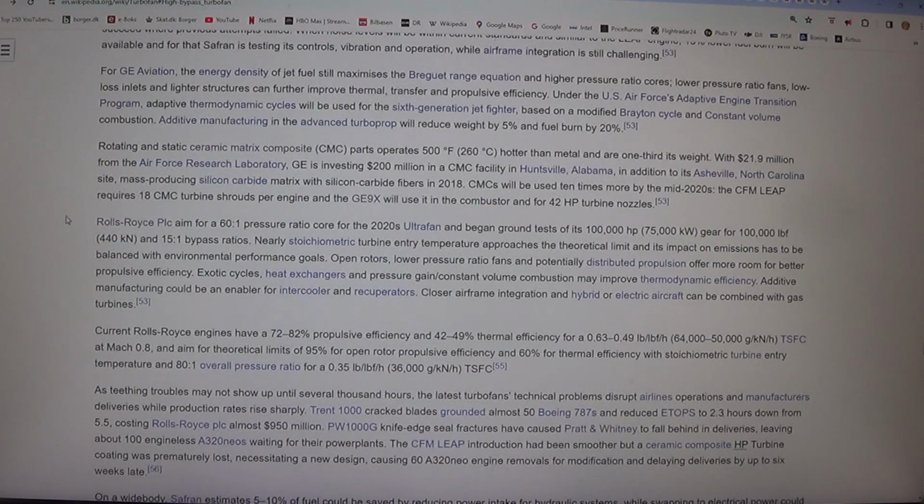In summer 2017 at NASA Glenn Research Center in Cleveland, Ohio, Pratt finished testing a very low pressure ratio fan on a PW1000G, resembling an open rotor with fewer blades than the PW1000G S20. The weight and size of the nacelle would be reduced by a short duct inlet, imposing higher aerodynamic turning loads on the blades and leaving less space for soundproofing, but a lower pressure ratio fan is slower.